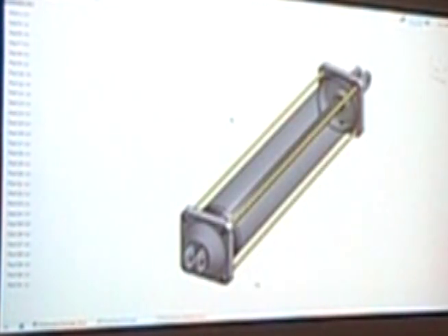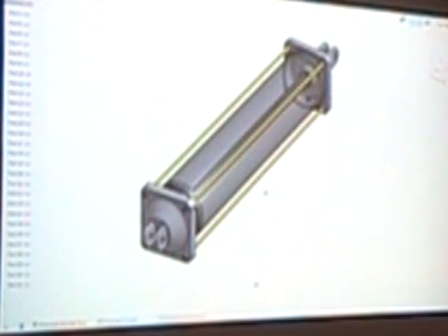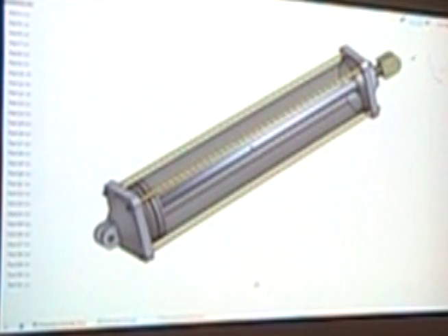I'm just trying to bring something up here. Onshape is very capable of handling this. So when you're doing assemblies, it's important to give the parts real world constraints, like a bearing is going to turn around a shaft, a lever is going to work around something, a shaft is going to move in and out of a hole. Let's see if this works.